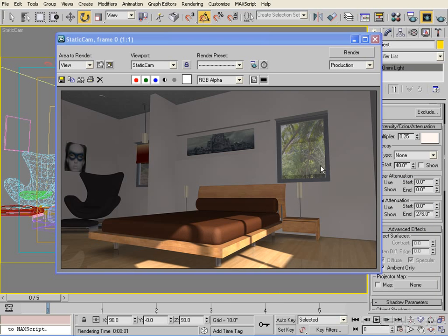There will be some light spilling in through these windows, and at the moment our key light is not visible as a light source. It's actually just the product of what the light is doing when it hits surfaces, because it's a direct light. It's a target direct light. So we're only getting the product as it hits the surface. So we need to emulate the sort of spilling of that key light from that key direction into the room. And that's what we'll move on to now.